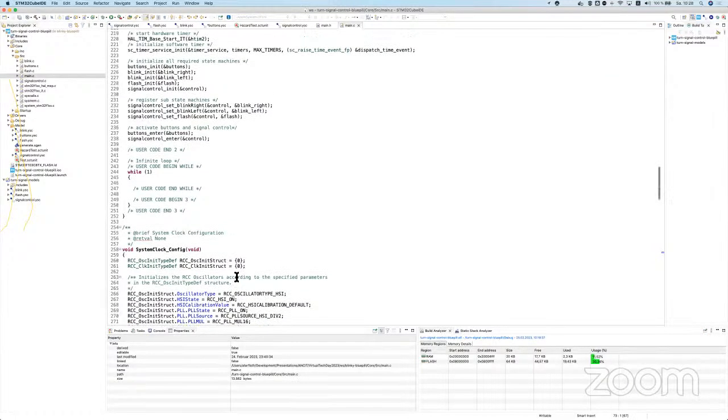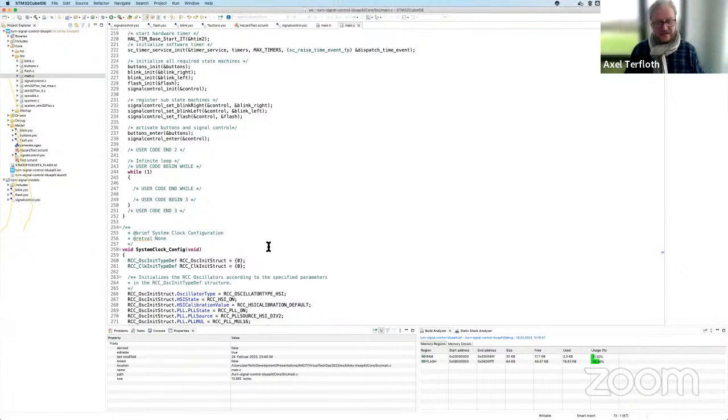So that extends me to another question, Axel. How about AUTOSAR support? If we are able to build the application using modeling, will it be able to simulate a BSW stack for testing? Is there an option for that? No, we cannot. That is not yet included. As you may have seen, the main application state machines are independent of the base software layer, so these are a little bit decoupled. The positive effect is that you can easily test those, but it takes extra action, and users of ours do that to integrate the base software layer.